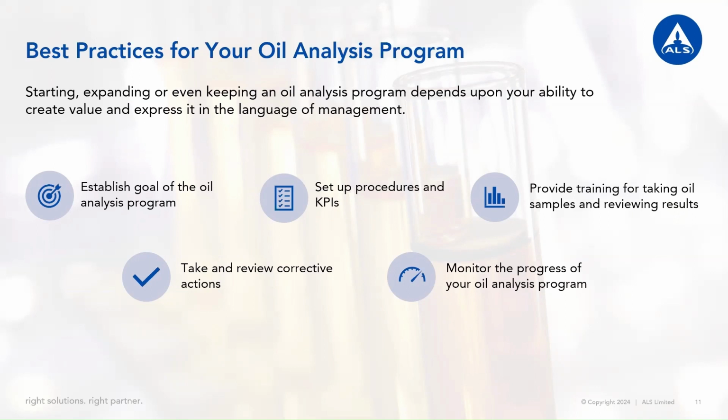3, provide training. Accurate oil analysis results require training to understand and training to take the samples properly. Integrating this training into your onboarding procedure will make sure that the results you receive are actually meaningful.